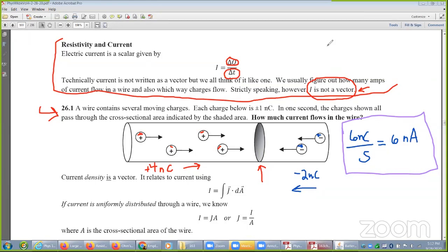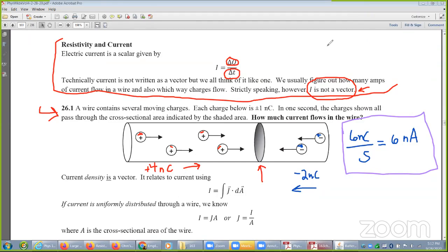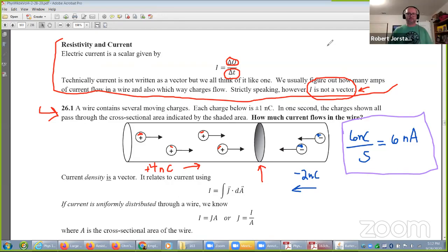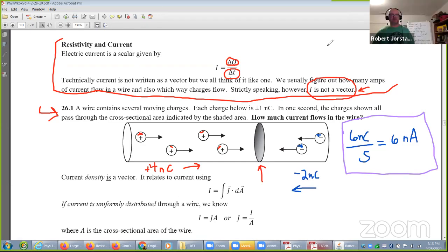Maybe this happens to be indium gallium arsenide and their holes. It turns out in different materials, effectively the absence of electrons can move, and that behaves just like a positive charge. Those materials are called semiconductors, and those absences of electrons are called holes, and they move just like electrons, except they have a slightly different mass. So you could imagine an emptiness moving throughout a material, like a bubble, except it's a positive bubble. Good enough, Ryan? Yeah, that's really interesting. It is cool, and we can talk more about it later.